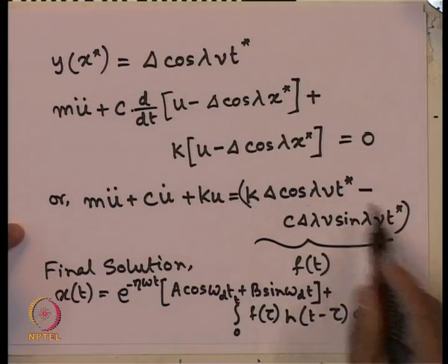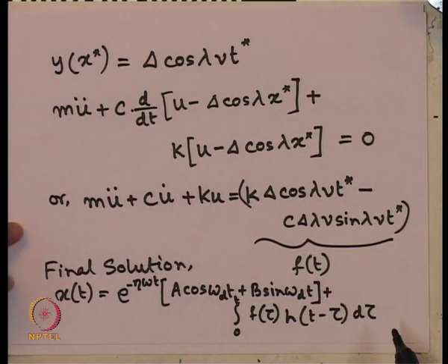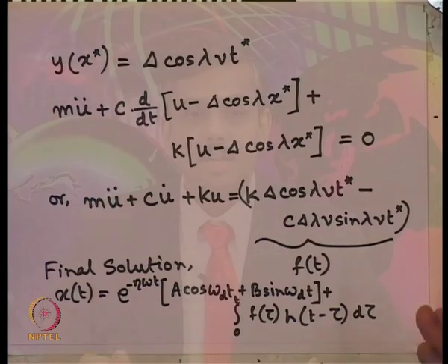So, this we are considering of f of t. For any arbitrary load, this is the final solution. You can put this expression of f of t and get this integration done. Suppose it is starting from absolute rest condition, you use the Duhamel's integral and get the solution. So, that is the way we can find out the response of a moving vehicle on ground, and this will give you an idea if you take any example problem. Later on we will see.